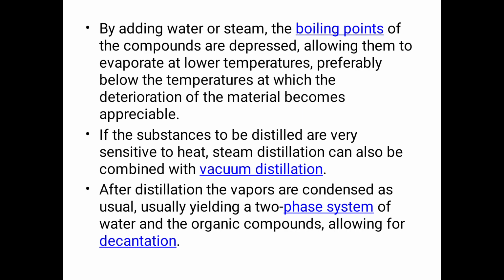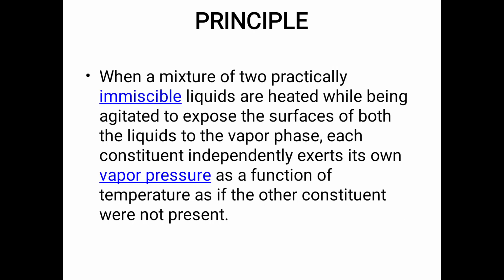If the substance to be distilled is very sensitive to heat, steam distillation can also be combined with vacuum distillation. After distillation, the vapors are condensed as usual, usually yielding a two-phase system of water and organic component, allowing for decantation. The principle of steam distillation is that a mixture of two partially miscible liquids is heated while being agitated to expose the surface of both liquids to the vapor phase.